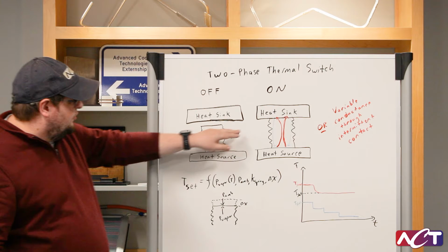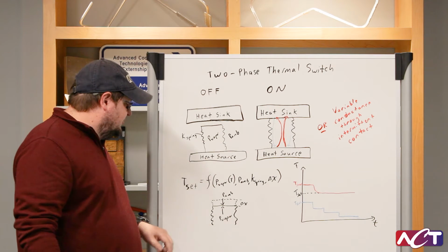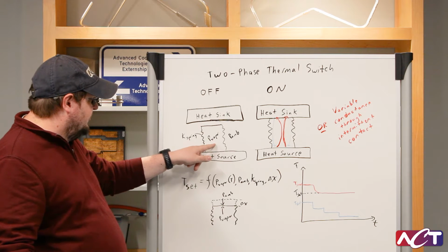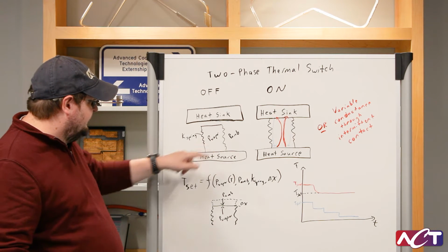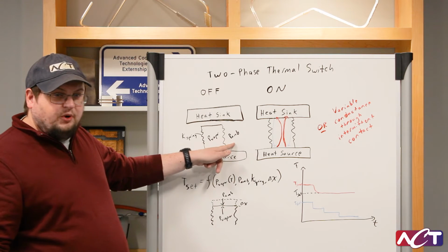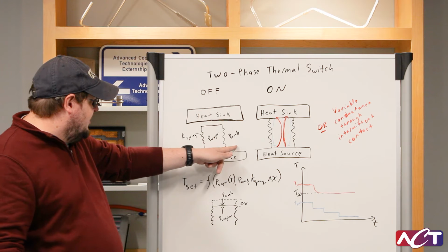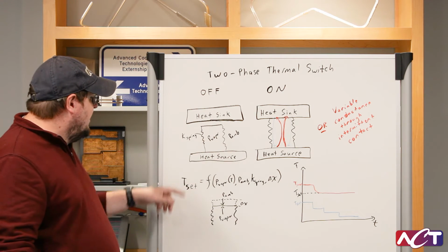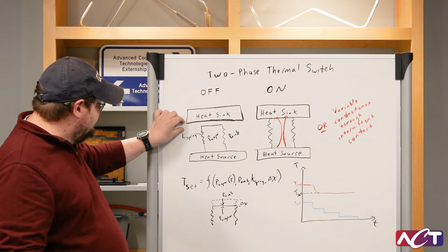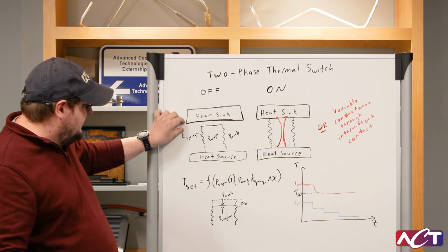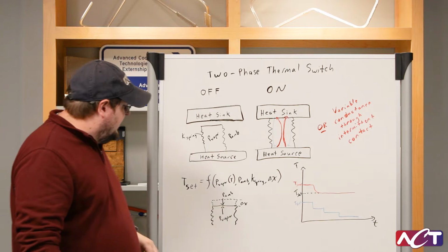The temperature at which the bellows contacts the sink is a function of a few different variables, one being the vapor pressure of the fluid, which falls along the saturation curve for that particular fluid. The other is any exterior pressure. This could be inside a pressurized container, or it could be in a vacuum, for example, if it's being used on a spacecraft. And then there's the spring constant of the bellows, and the initial distance between the sink and the end cap of the bellows.